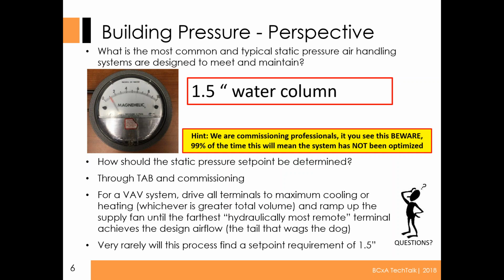You have to find that through TAB and the commissioning process, driving all the boxes open and figuring out how much air you actually need for the furthest or most remote boxes to have enough air to meet their set point. So the air handler is where pressure comes from for you to be able to pressurize your building.